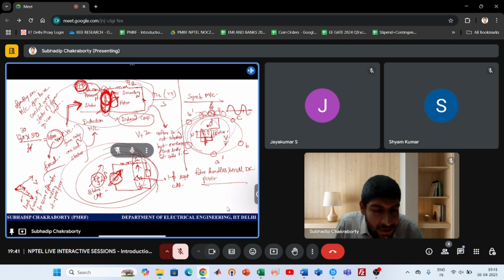So power factor control is very important, and that's why as an electrical engineer you learn power factor improvement techniques. All the var compensators, and so many things you learn in power system, like transposition of transmission lines to reduce the inductance, and all forms of things to provide support or to improve the power factor, maybe at the load end or the generation end. All the game that is going on is only to improve the power factor. Power factor is a local thing. At a particular node, we define the power factor, not at every point.